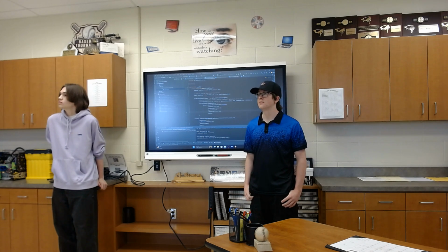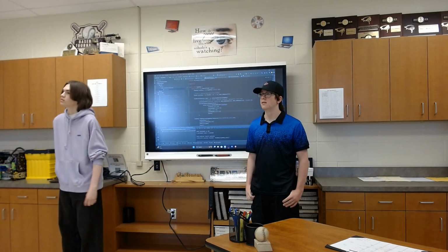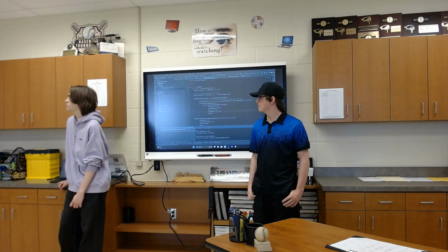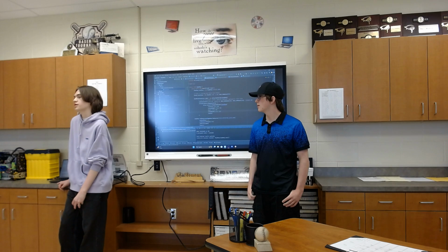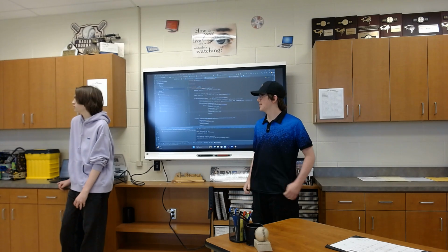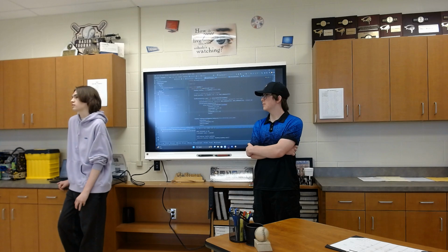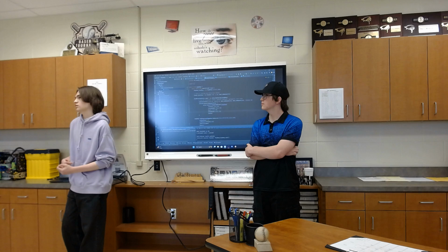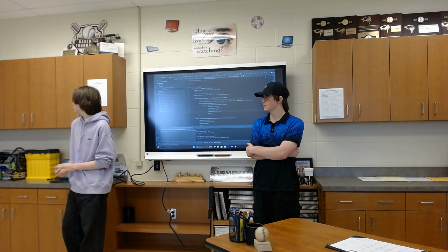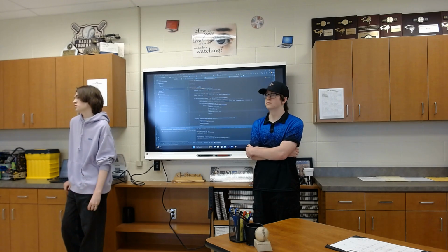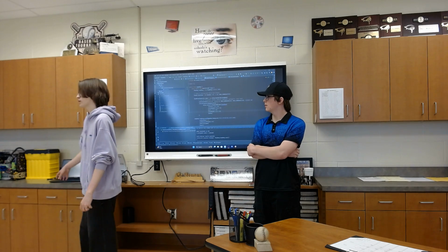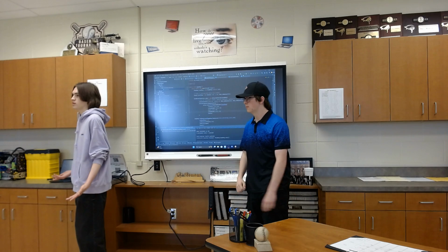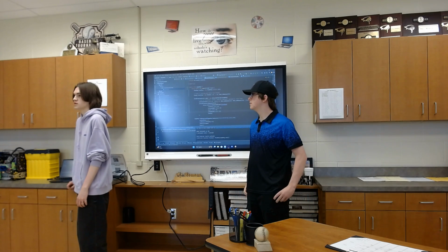What does the pricing look like for the dead wheels that you mentioned? So the goBILDA dead wheels are about $230 to get a set of 3, but you don't need all 3. You can use only 2, but if you want a very accurate heading of your robot, you would need 3. If you only have 2, you would have one in the middle and one on the side. When you have 3, you have one on both sides. And we found it to be a lot less efficient to have 2 instead of 3.